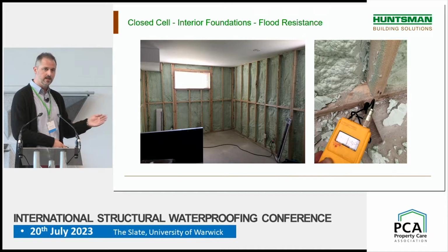During 5 days following the flood, this house was dehumidified and ventilated. So when we came on site, we took spray foam samples, measured the humidity content of these samples, and verified the adhesion as well. So the spray foam had not absorbed any water. So we were able to keep the spray foam.